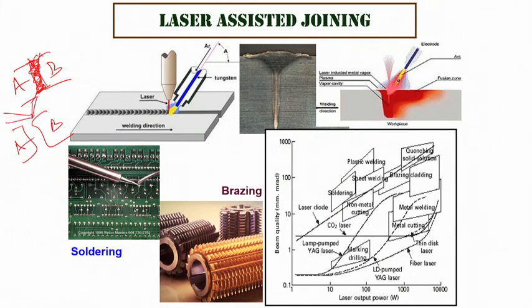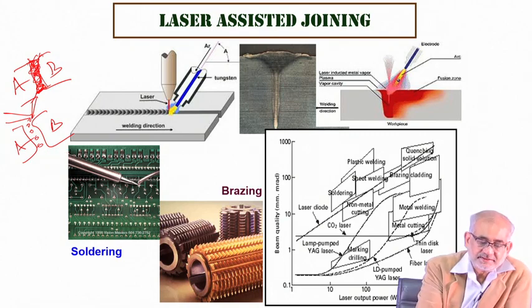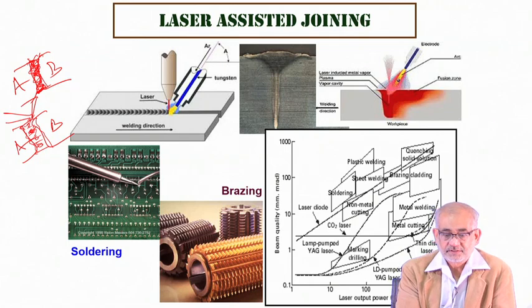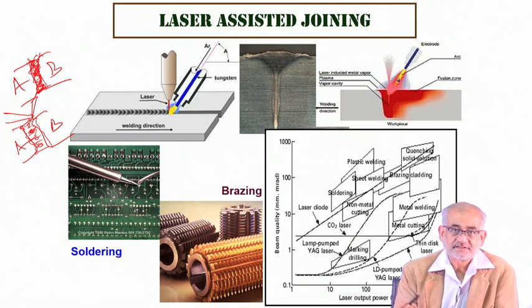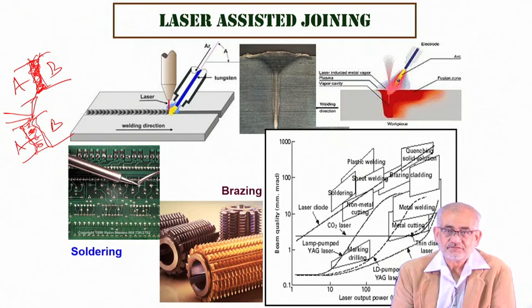and use the laser beam to hit the filler metal so that the filler metal melts and allows droplets to trickle in and eventually fill up this gap in between. So when this liquid fills up the gap, this liquid wets with this solid A and B well, and in the process can create a very good soldered or brazed joint. If the temperature is higher, you call it brazing, typically used for copper alloys, or you can do soldering, typically for metal to semiconductor or semiconductor to semiconductor joining, let's say easily below 300-400 degrees centigrade. So roughly speaking, about 400-450 is a cutoff point.